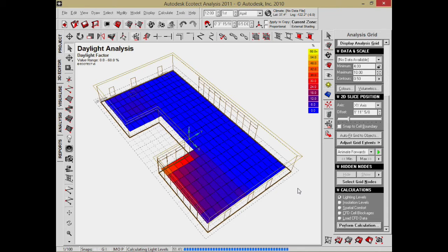For the LEED qualification that you mentioned, is that it needs 75% at a certain time of day? Actually, the goofy thing about the way daylighting analysis works is it's time of day independent. They just assume an average daylight value throughout the day. There's a standard amount of what they consider to be sun in the sky, and it's considered to come in from all sides equally. So it's a little different. It's not sunlighting, and sunlighting is very specific to time of day and location. But you notice daylighting comes in from the north as well as from the south. Even in a room, if you look at a north window, there's still light coming in, even if it's not sunlight. So it's time independent. It's day independent too.